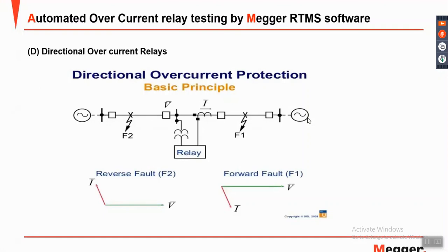And this is only an example also about the forward and reverse of the overcurrent relay as a direction. And the only thing here you see is that we are not using only CT, we use also VT to do the polarization.